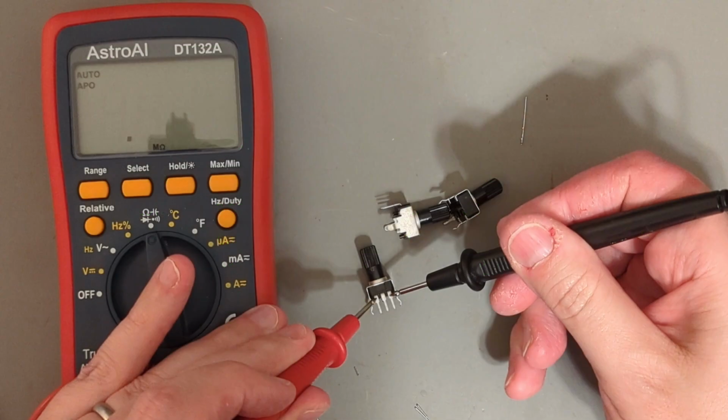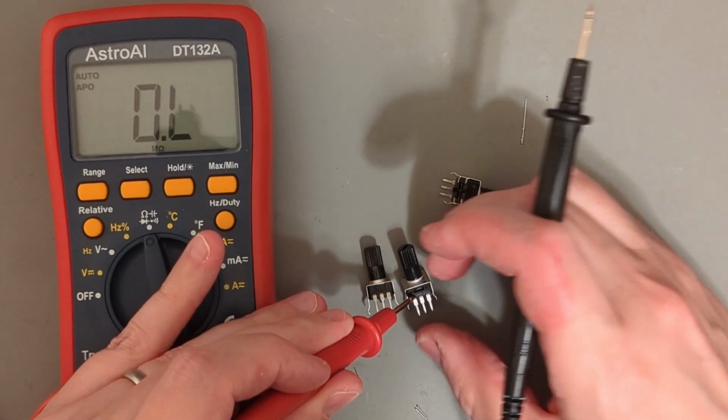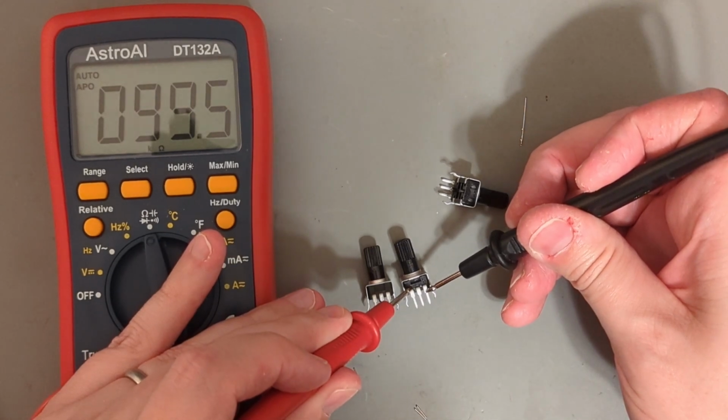If you're not able to tell what value a resistor is, you can always just measure it with a meter, but it's best to do this when it's removed from a circuit. If it's inside your circuit, other things can influence your measurement.